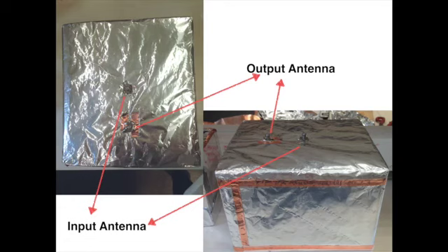And I put the two antennas on the locations I described on the previous slide. Basically, I had a 6 centimeter long copper wire for each antenna, and I soldered it to the middle part of the port, as shown, the square metal piece. And I soldered the ground plate of the port, which is the square part, to the cavity resonator using the copper tape, because you can't solder on aluminum, and it actually just burns. The copper tape also makes it more firm, because we don't want it moving and changing direction inside the box.